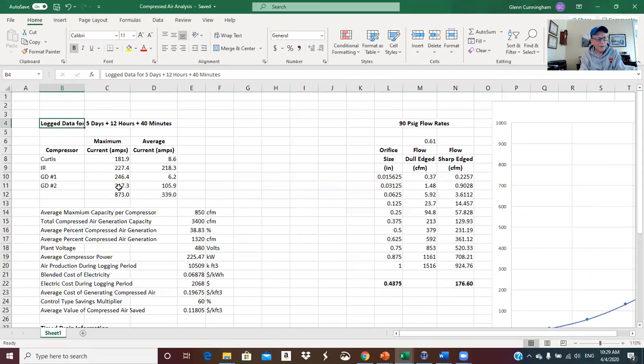When you look at the timer settings, all of them are set to blow 10 seconds and be off for 30 seconds. So that's a 40-second cycle. The 10 seconds that it's on divided by the 40-second cycle time is 25% of the time this thing's blowing. And they've got 4 of them manifolded together, so that's equivalent to having one of these things blowing continuously. So this is a 7/8 inch leak all of the time.